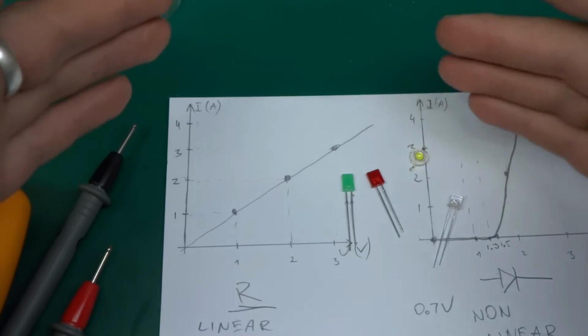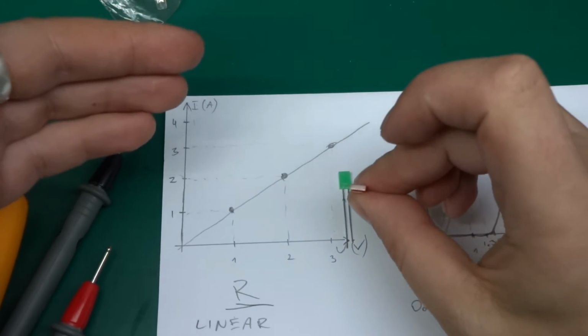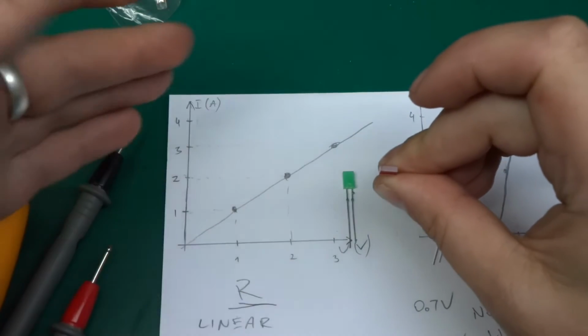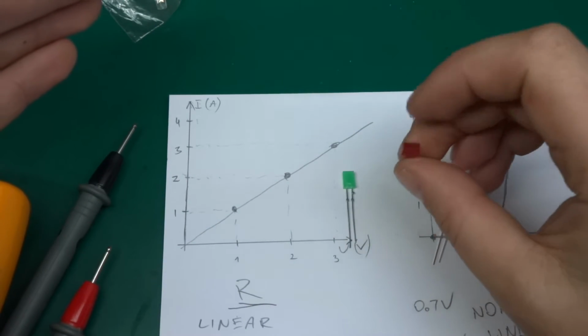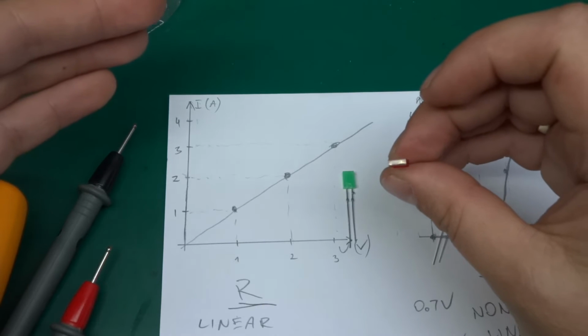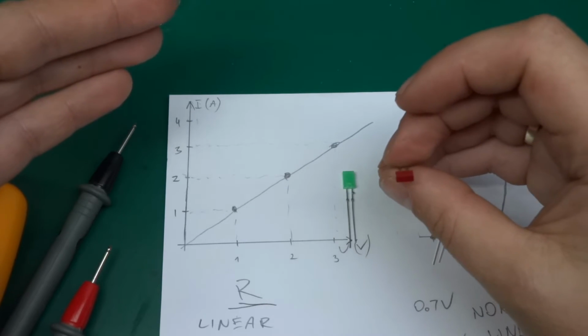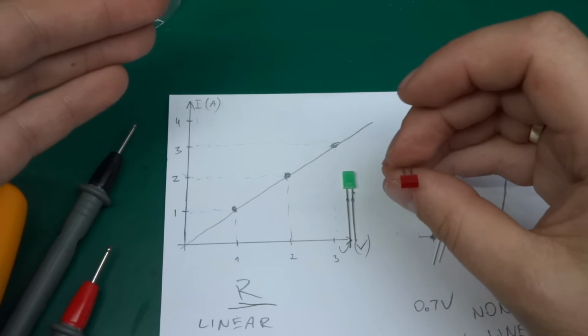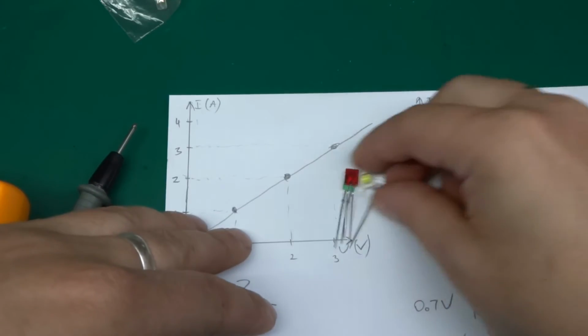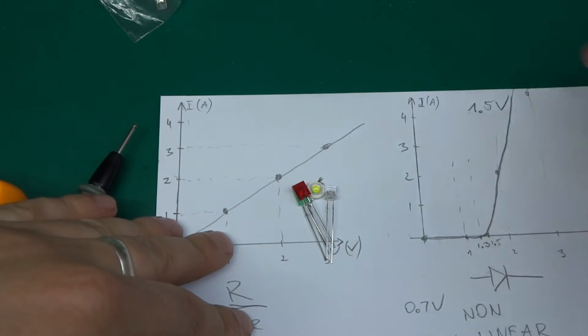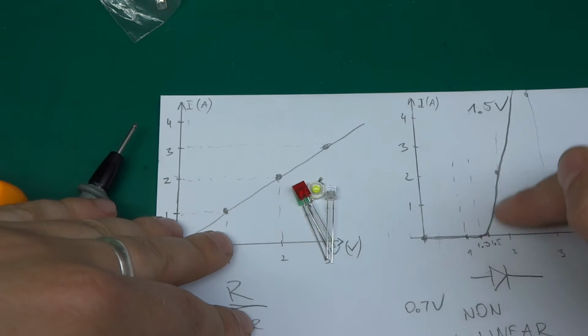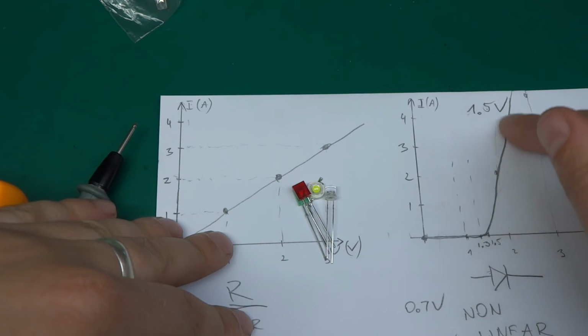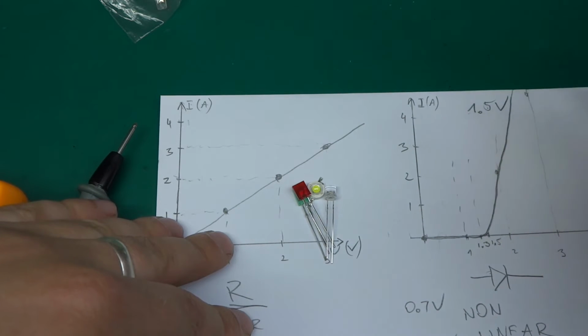It's really simple, because what's the special property that differentiates an LED from a rectifier diode, for example? Well, it emits light, so it will show you that it's working as long as you put some current through it. Now the danger is, if you go over the forward voltage with too much current, and I'll show you that in a moment, you'll start putting quite a lot of current through the LED, sometimes as much as your power supply is capable of. That will kill your LED instantly.